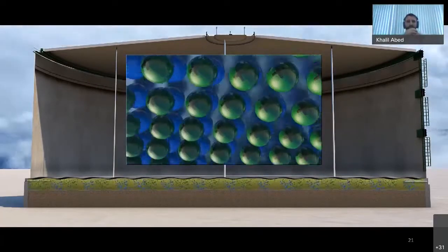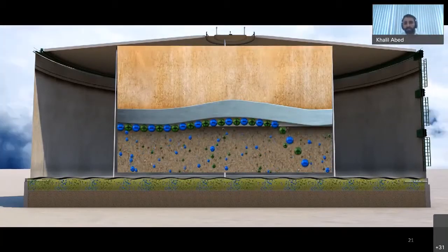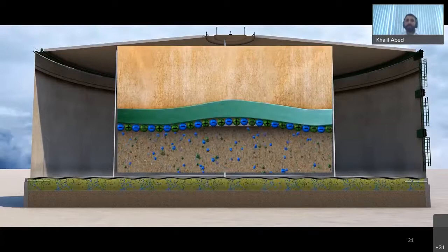The vapor phase corrosion inhibitor molecules will absorb onto the surface and then form this protective layer, again suppressing active corrosion rate on the tank bottom plates surface.